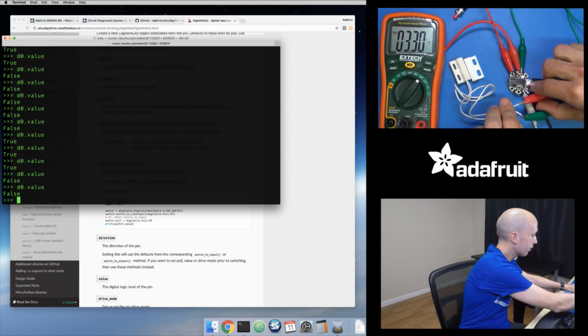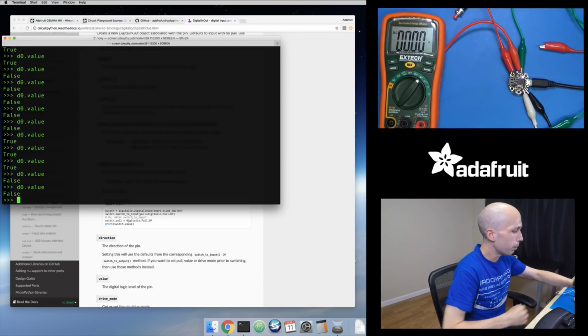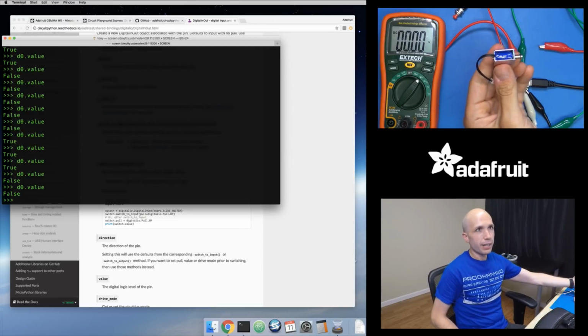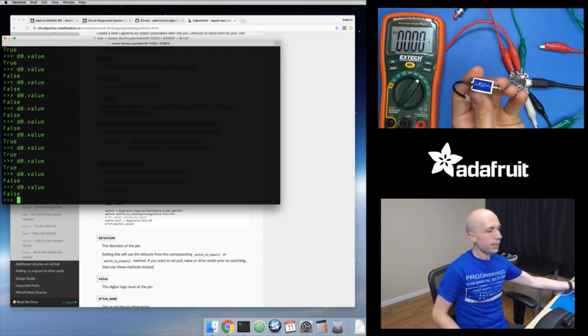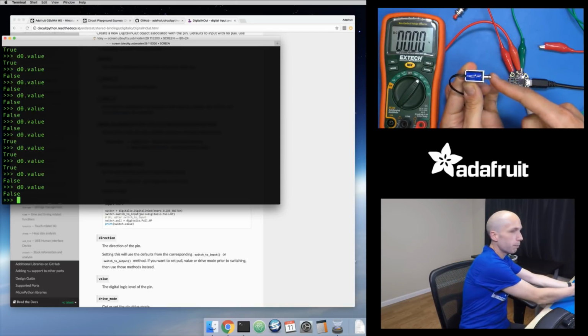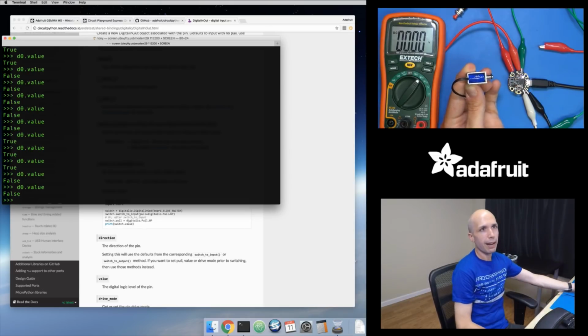Let's go back and look at the outputs again. And I'll just mention a few digital outputs that aren't just LEDs. So you can do more than turn on an LED. You could actually control something. So there are things like these. This is a solenoid. This is a little micro solenoid, where basically it's a device. When I apply voltage to it, there's a little plunger right here. And this plunger can get pulled in or can get pushed out. I think on this device, I want to say the plunger gets pulled in when it applies voltage to it, but it might be reversed. There are all different types of solenoids. But this is kind of cool if you're trying to actuate something.